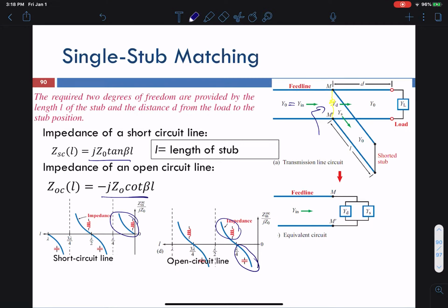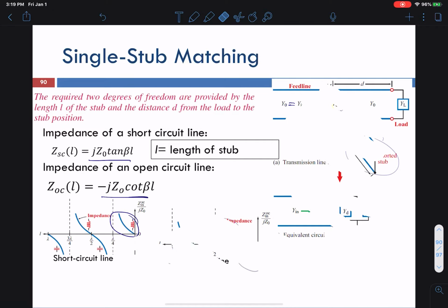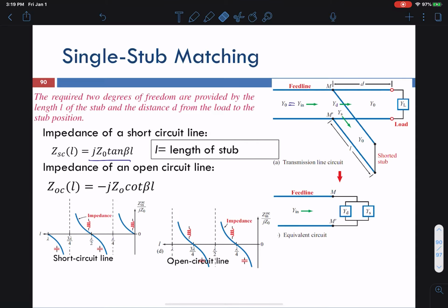So now, instead of a real capacitor or inductor, can we use a short circuit line or an open circuit line? If we have a very high frequency, this line length could be small, smaller than the actual part. Then we can use a short circuit stub or open circuit stub to do the matching instead of a real capacitor or inductor. So how do you do that? We're going to continue the last problem we did. So let's go back here.